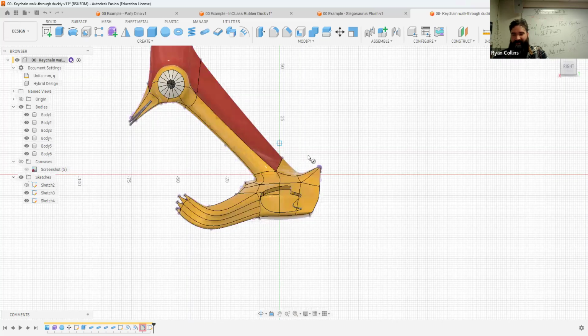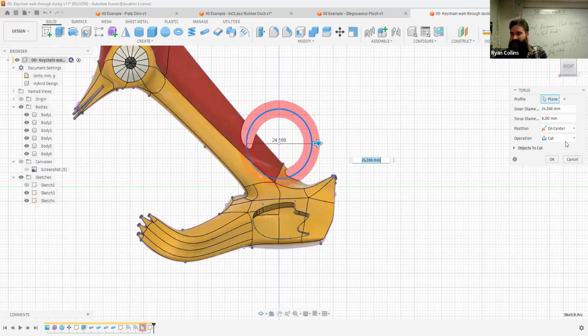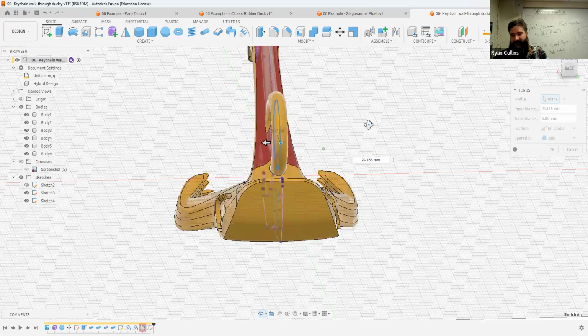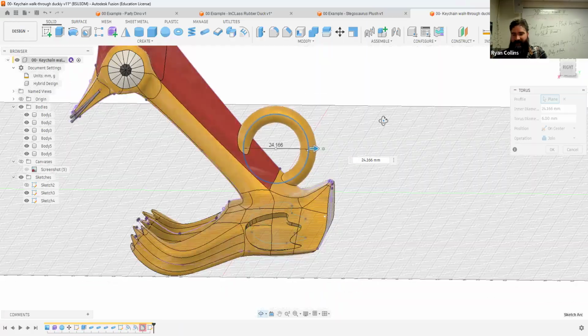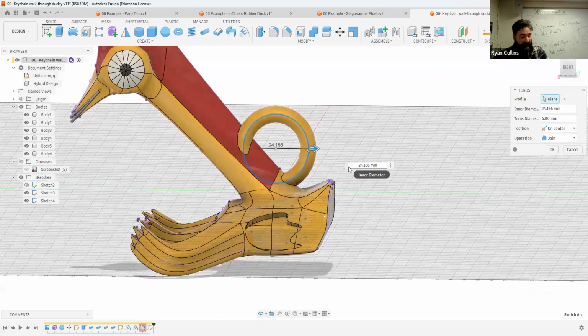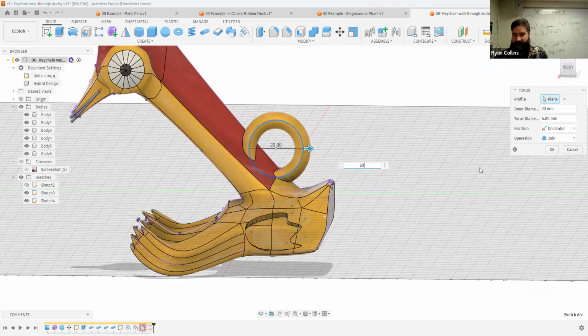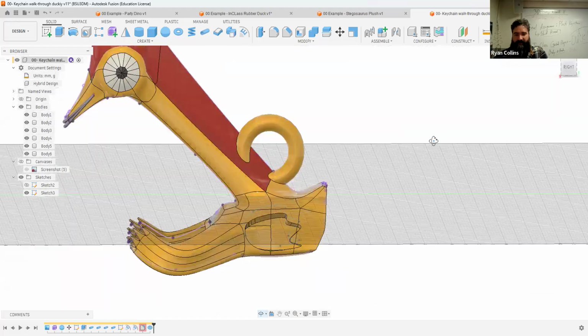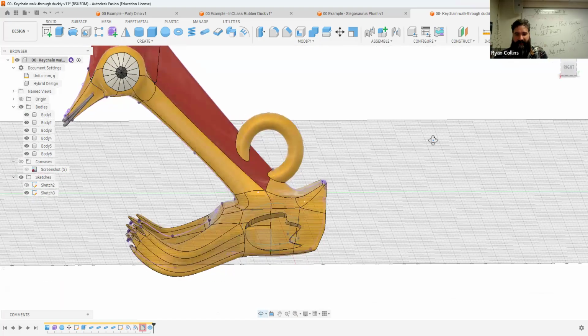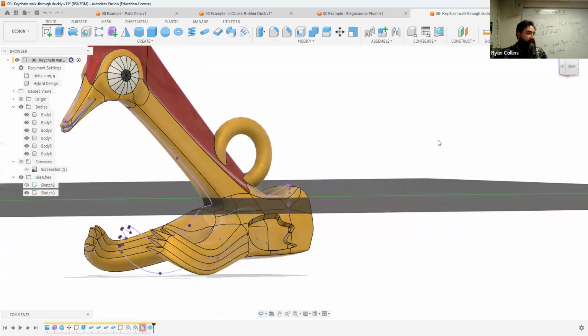A Torus is just basically the donut tool. Let's do a join. And you can move that wherever you see fit. A 25 millimeter is kind of excessive. No, actually, that's pretty good. So, I don't know. We'll just make it an even 20. And there we go. That would be a reasonable place to put a keychain through. Or right through its skull. That's up to you.